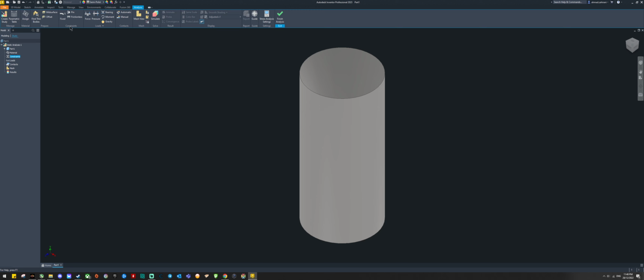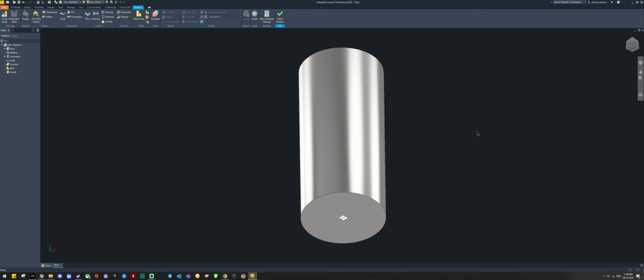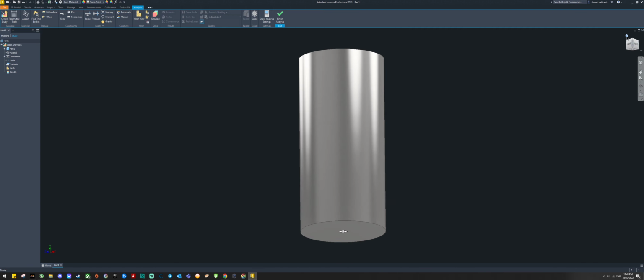So look at the constraint option and select fix, and select the bottom part of this component and select OK. So what we have done is that we instruct Autodesk Inventor to say that the bottom part of this component is fixed on the wall or on the floor.